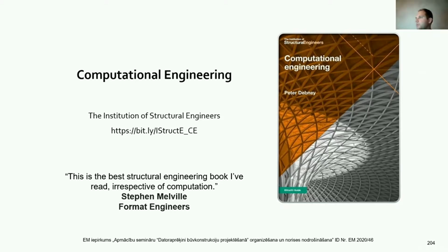Okay, so then there is a specific question regarding precast concrete: would you recommend setting Poisson's ratio to 0 when doing structural analysis of precast concrete structures? Well, the concrete itself does have a Poisson's ratio, so why would you set it to 0? I mean, if you're dealing with one-dimensional elements, the Poisson's ratio has no effect anyway.